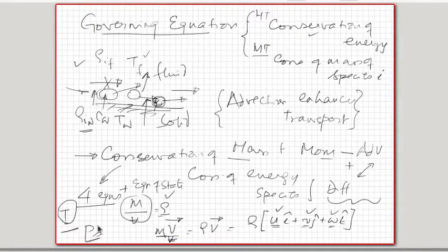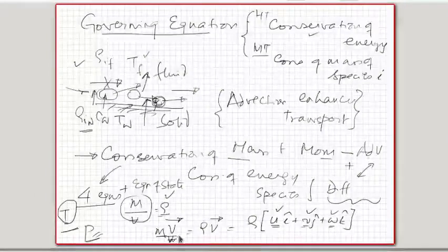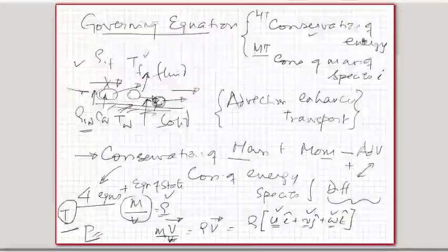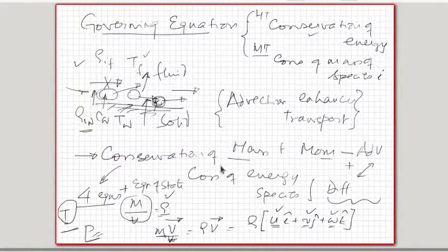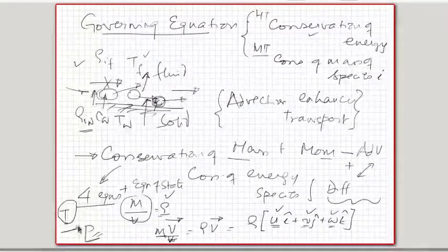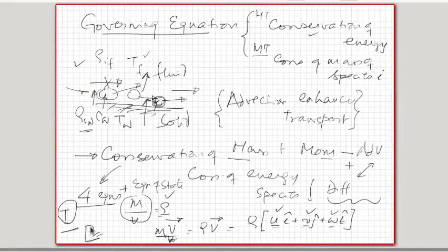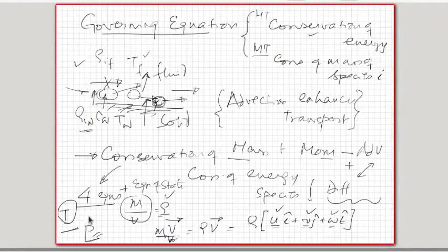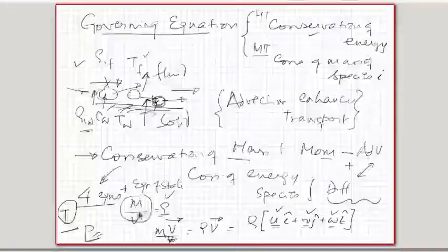So then the energy equation gets coupled with the momentum equations, or the equation of state gets coupled with the momentum equations. Otherwise, normally the conservation of energy equation can be solved independently of the conservation of mass and momentum equations when the density is not strongly affected by the pressure and temperature. When the density is affected strongly by the pressure and temperature, then you either get natural convection flows where the energy equation has to be solved simultaneously with the momentum equations, or you get the compressible flows where the pressure has to be specifically accounted for, and we solve for the energy equation and the conservations of mass and momentum and get the pressure from the equation of state. So this is how this set of equations gets closed.